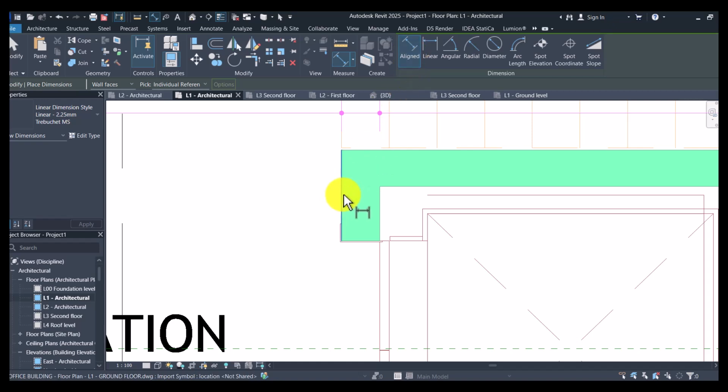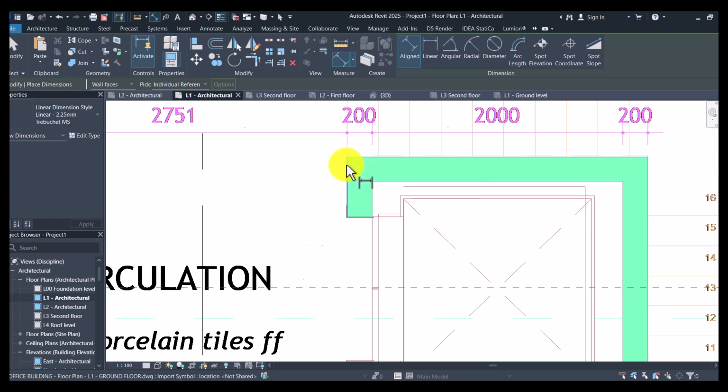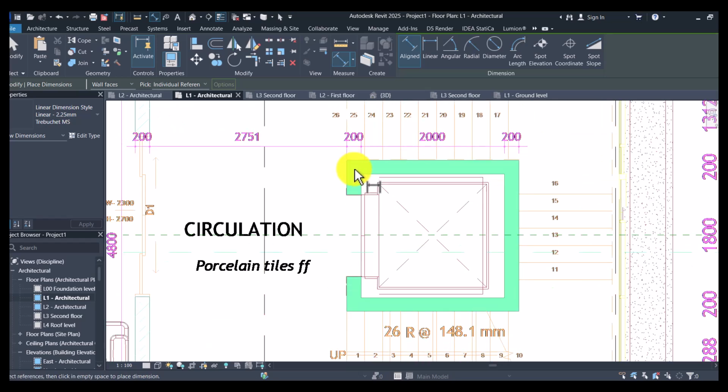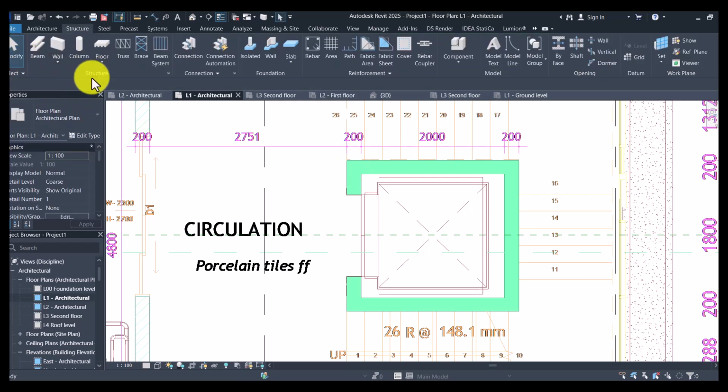So right now, we do not know if they are strong enough or weak. But for the meantime, we're going to take the same thickness of the walls. So the design will tell us if they are sufficient. So a quick reminder, what we are doing now is coming up with a structural layout, a model that is ready for exporting into ETABS for design and loading.